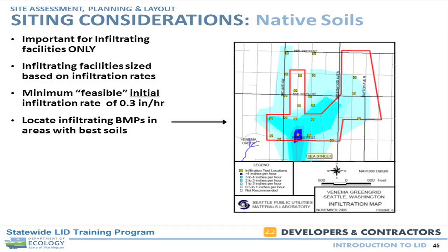It's not a determination to say you cannot build bioretention in soils that infiltrate less than 0.3, because technically you can. I have worked with geotechs very comfortably down in the very small numbers, and you can design accordingly. That's the threshold from a policy point of view that has been established, where if your initial infiltration rate is 0.3 as measured by your geotechnical engineer, Ecology says you don't have to do bioretention. Above 0.3, you have to do it.